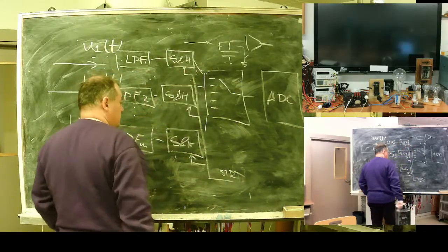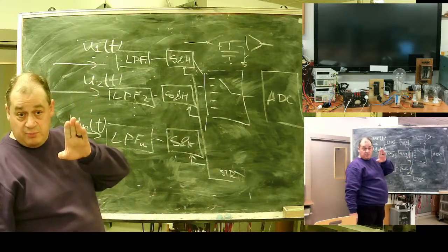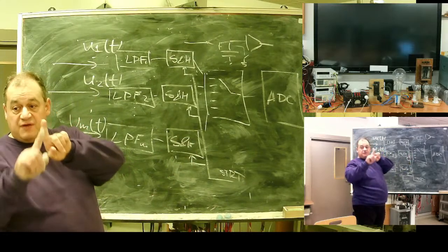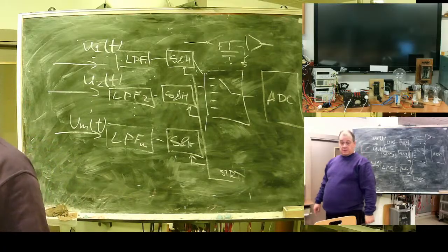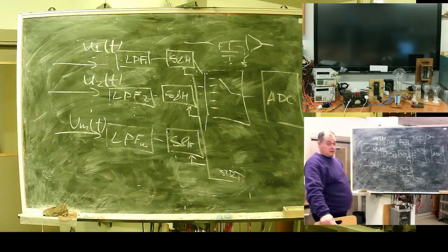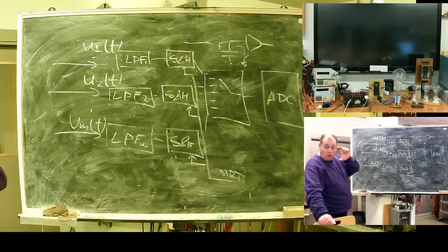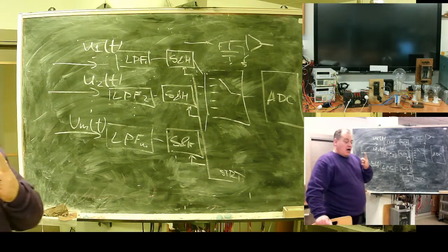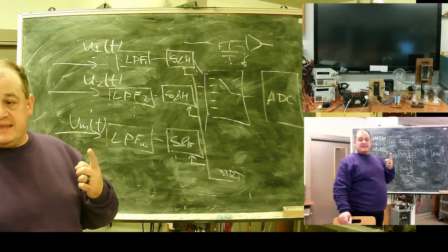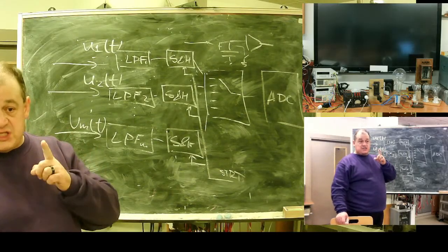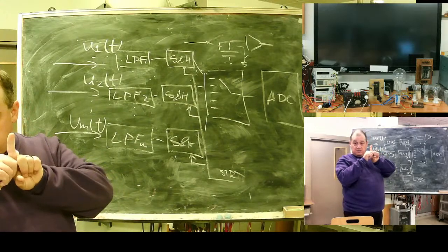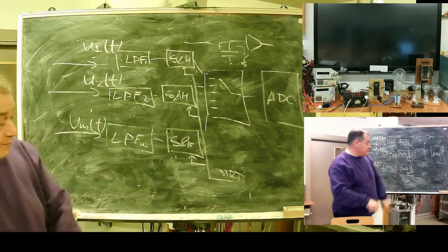A release signal is sent to the sample and hold, and the cycle begins. Because we have a time shift in measurement, sample and hold is a special circuit with a storage capacitor which stores the voltage. It guarantees, how to say, uniformity or integrity of measurements: that all voltages are measured at one particular time moment.